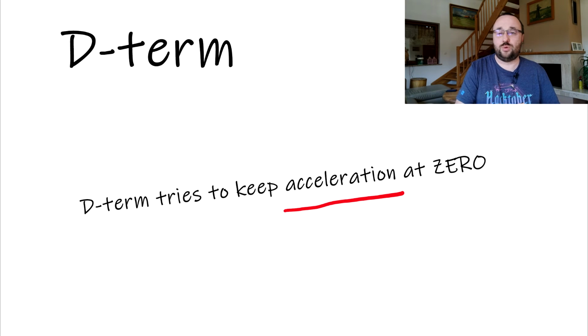If the D term is computed from the measurement, then it always acts like a damper, because when you start the maneuver, start the change, it will try to counteract it and not allow the object to accelerate. If the D term gain is too high, it might overdamp, and if it's too low, then on the other hand the response can be very mechanical. Instead of slowly accelerating towards the set points, you get very mechanical, rapid movement. The same thing happens at the end of the maneuver, when we release the stick, and how the response should then be handled.